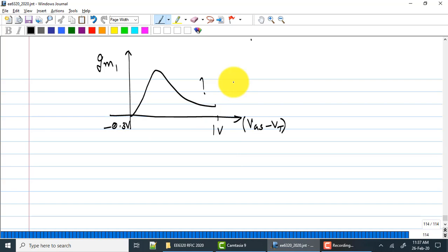So let us assume to a first order that you are not going to set VGS minus VT less than 0. Because what you have done is you have plotted for the subthreshold also. It is perfectly acceptable to design an LNA with the device biased in subthreshold. Let me assure you. If you come back with the LNA project and tell me the device is actually in subthreshold, perfectly fine. I'm okay with that.